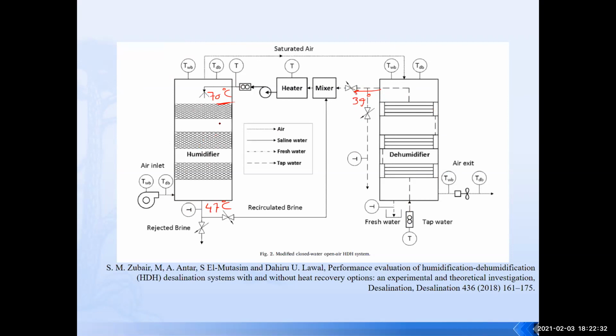And then we said, why should we be doing that? Why don't we take this water, which is hotter, and reroute it back again and make this water only a backup? When you look at it, it would make much sense, because why should I heat the water from 39 to 70, whereas I can heat it from 47 to 70?